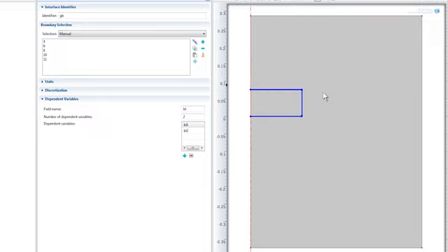This is a multiphysics analysis solving for multiple variables, including the temperature field histories of the puck and liquid, as well as fluid flow variables for a two-phase turbulent bubbly flow. In addition, the boiling layer, which I just described, is modeled using a custom proprietary set of boundary equations.